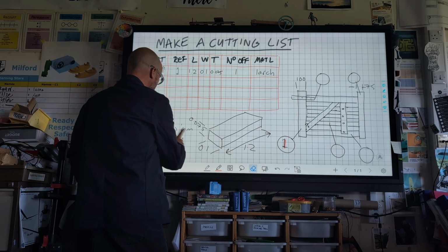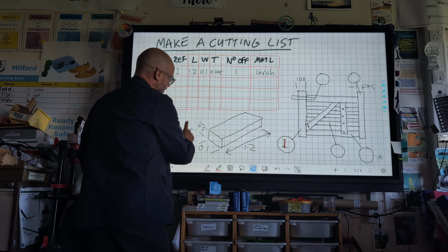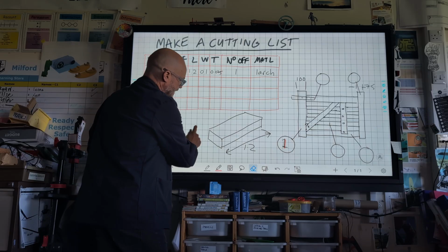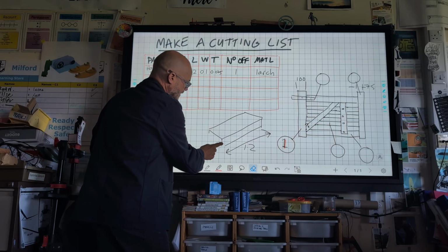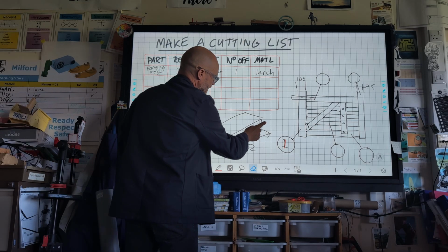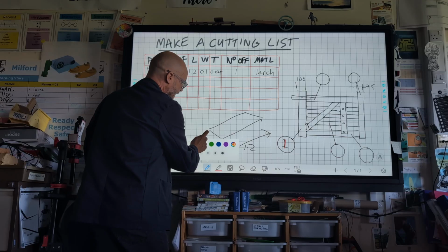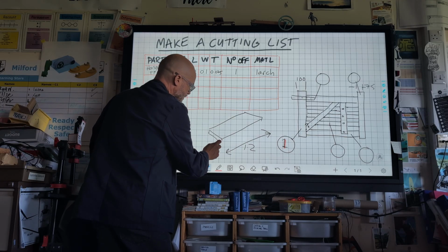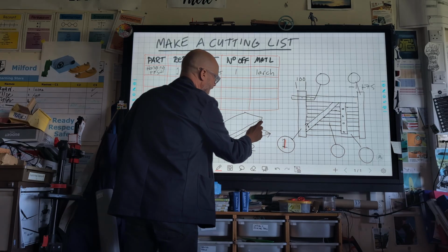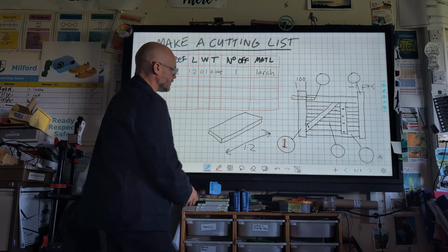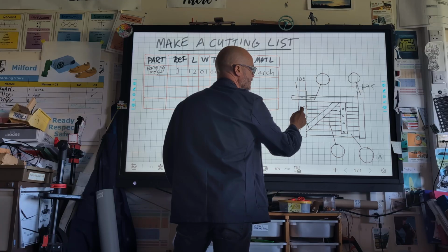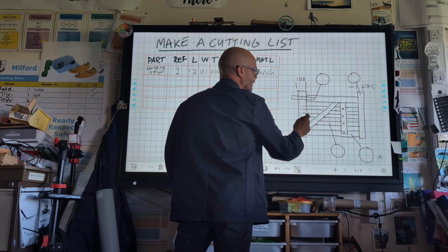So my other piece I'm going to do is one of the slats, and I'll show you why I'm doing that, the slat now, right? So the slat is made out of a piece which is narrower, okay? It's made out of a piece of 4 by 1 inch timber, okay? So here's my 4 by 1 inch timber, more like that. I'm going to keep the length at 1.2. I think it might be. When you measure the widths of these, be careful because you've got to include the tenons that go right through.